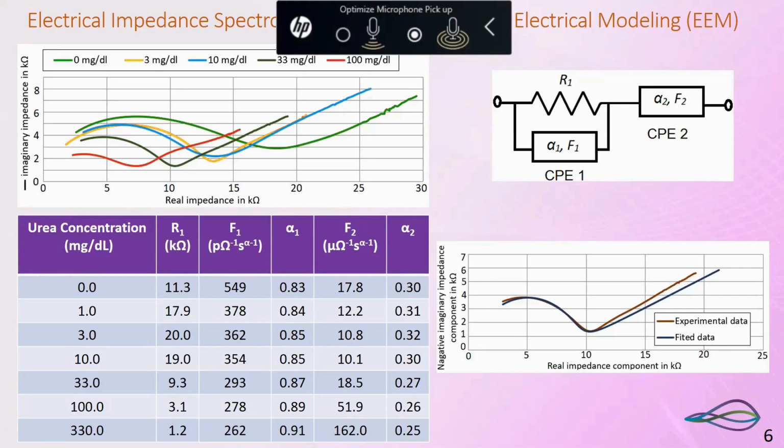So to get these parameter values, you have to take the impedance measured from 20 Hz to 2 MHz, then use the ZView software, and then you will have these parameter values. So you will say you are proposing a portable meter. So how would we do this?